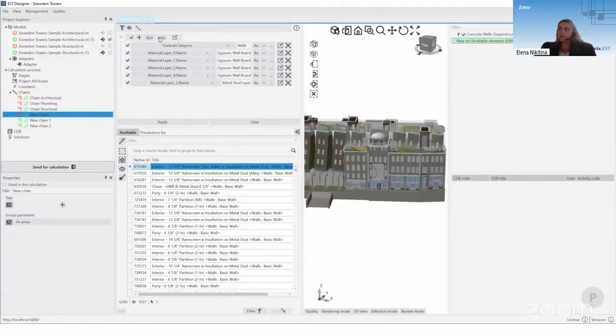If we put OR here, it will be quite different, because then we search maybe walls, maybe something with gypsum wallboards in the layer name. It can be other structures or something with the metal stud layer or something else. We need to put only AND here.